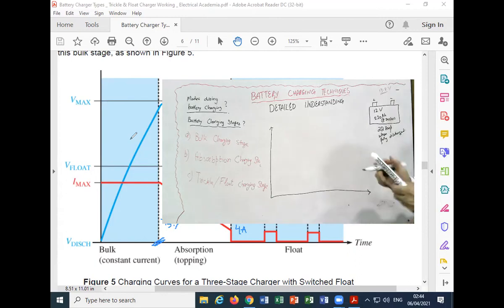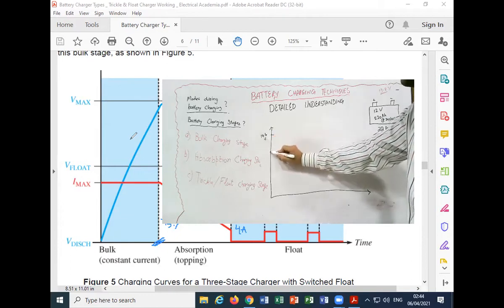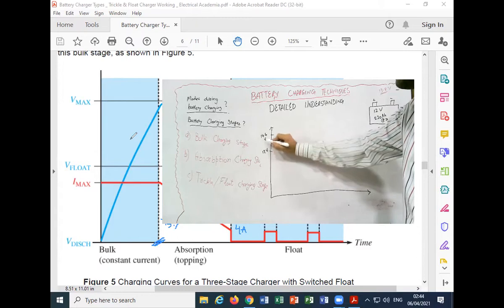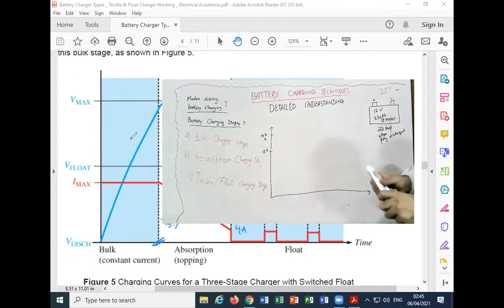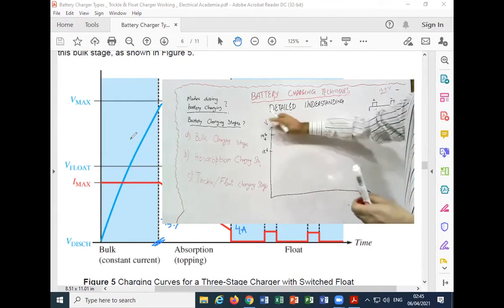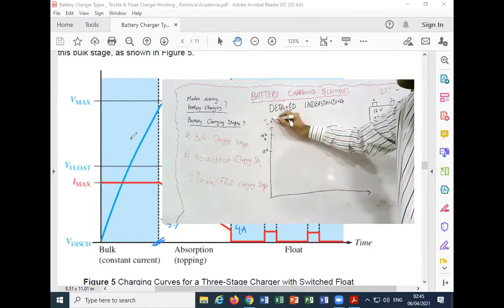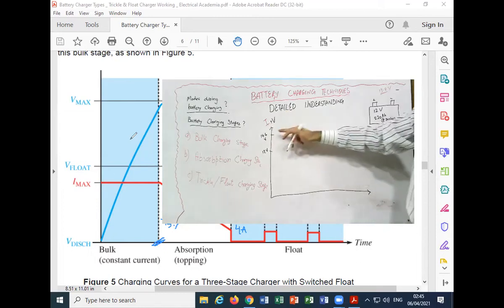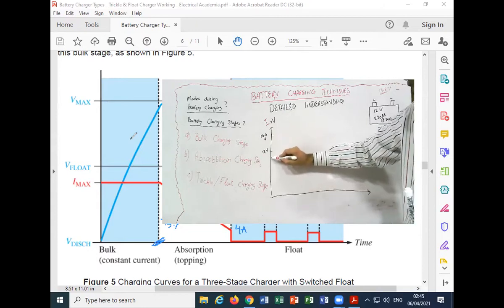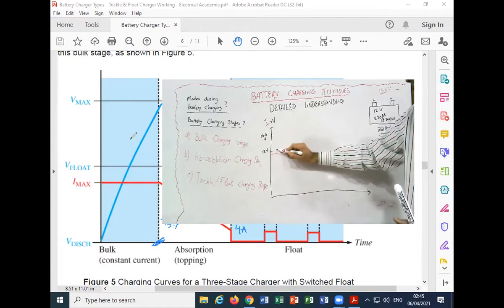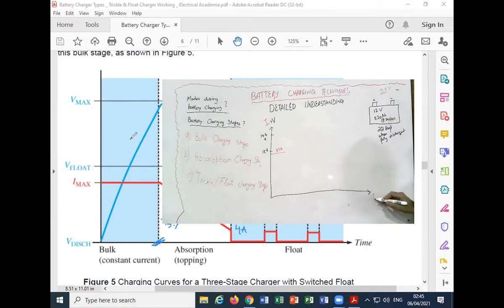Okay, so the battery charger is providing you with 14.6 volts, and this is the 12 volts, which is the voltage of the battery under the steady state. Now what happens, and I'm merging these graphs, the current versus voltage. You applied this voltage on the battery, 14.6 volts. Now the current will start from, let's say, 22 amperes, and here we have the time.